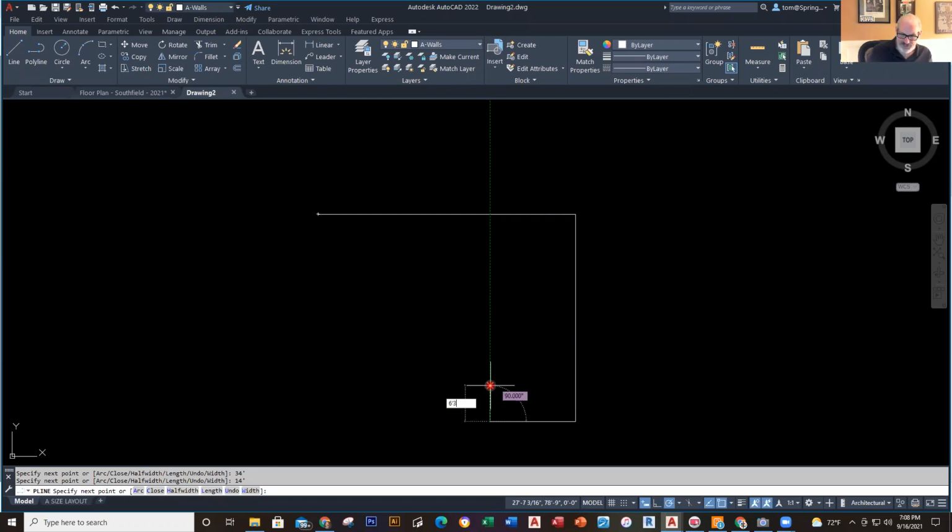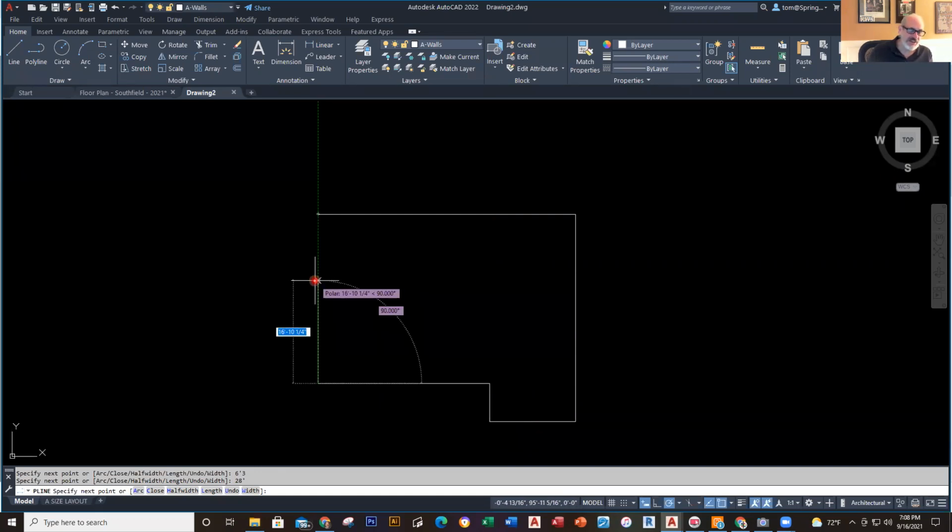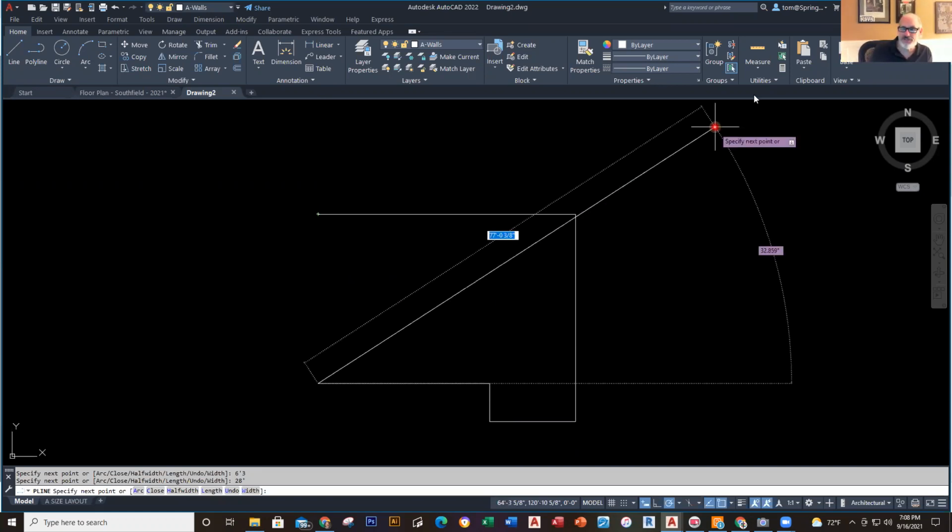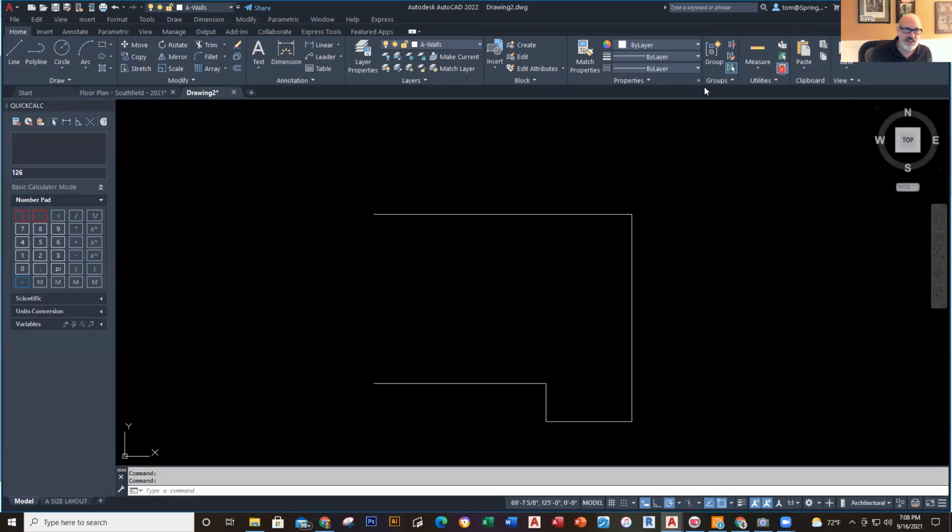And I realize you don't have this in front of you unless you're looking at it on your screen, unless you downloaded it, but I would recommend that you do that. And then I'll just right click, and now at this point, I have to put in the chimney. I can do this one of two ways. I could just count the dimensions up right here. So to draw the chimney, I'll give you this distance. Let's just do a little bit of adding right now. I'll pull up my quick calculator. Can I put in feet? I'm not sure if I can or not. I'll find out.